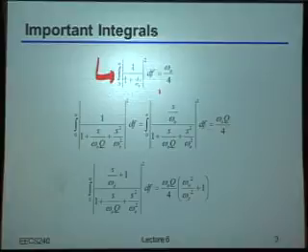Because unless you know what the exact transfer function is, you generally aren't working with brick wall kinds of things, right? It's not that you're interested in exactly the bandwidth from X hertz to Y hertz. You actually have some transfer function, some real filters that you've built, and that would tell you what the real bandwidth is. So again, once you know the transfer function, that's what sets the effective bandwidth that you use inside of that delta f term.